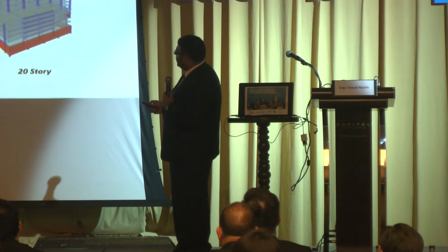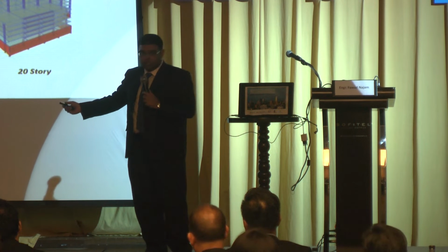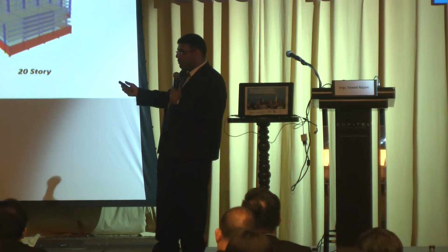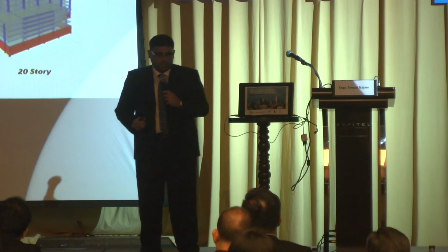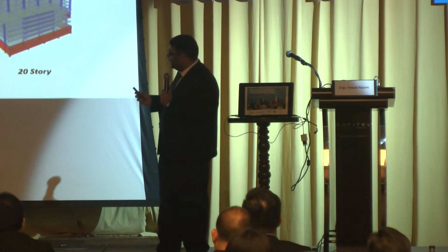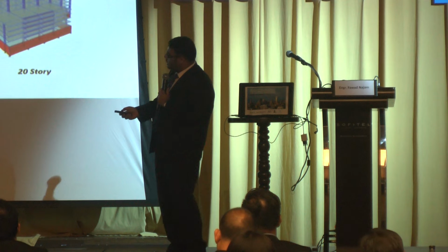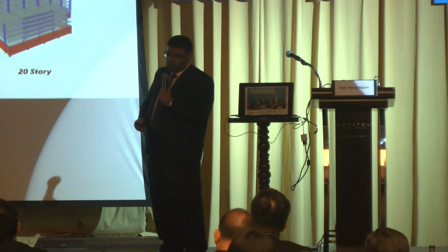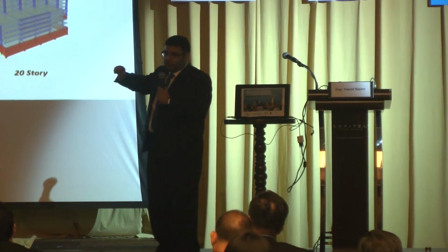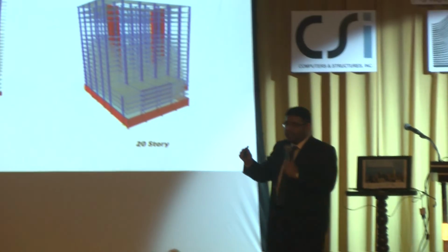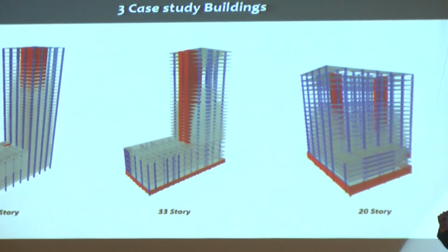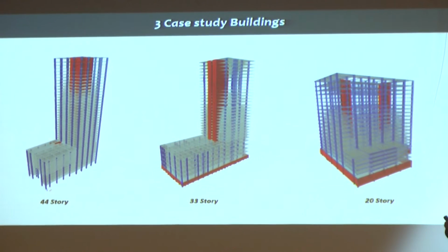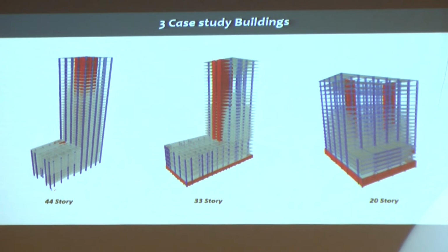We have applied this idea to a number of case study buildings in the last 3 or 4 years. I will present just quickly the results of 3 case study buildings which we selected. They are existing buildings in Bangkok as part of a project funded by BMA. The one is a 44-story building, and then 33, and the shortest one is a 20-story building. So we separated their modal responses to understand whether they experience the same amount of nonlinearity or different, or which mode deserves what reduction factor.